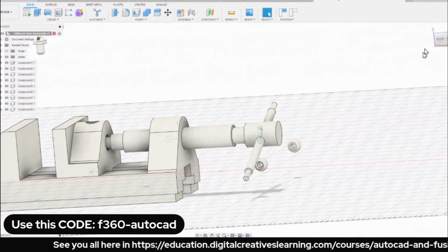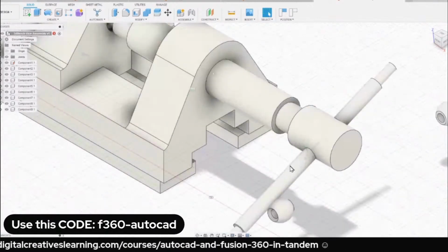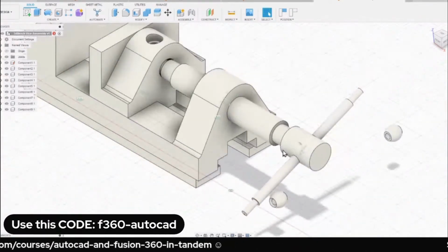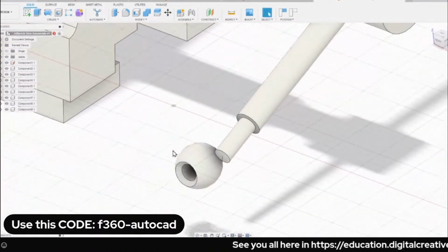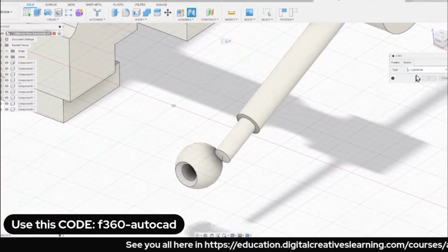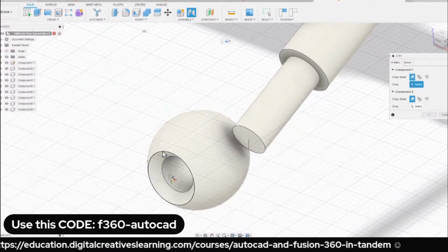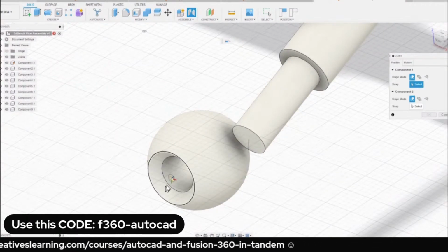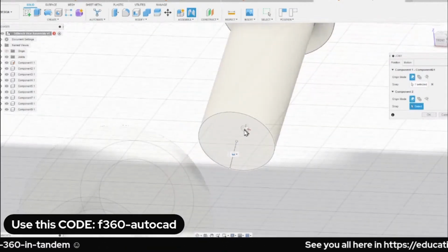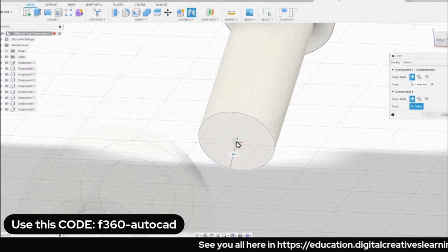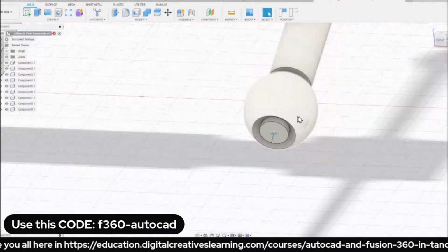So hoping you are following along because this would be our final exam. I want you to recreate what I did. So next step is to have this end pieces. Let me hit J. I think the appropriate for this is rigid. I'm going to, heading back to position again, hover over this edge. Hold control, selecting this joint origin and hovering over this face, holding control just to make sure, and selecting this joint origin. Left click. Selecting OK. Let's check.